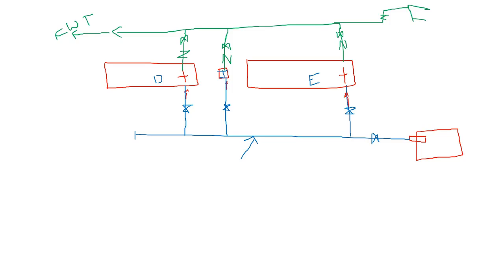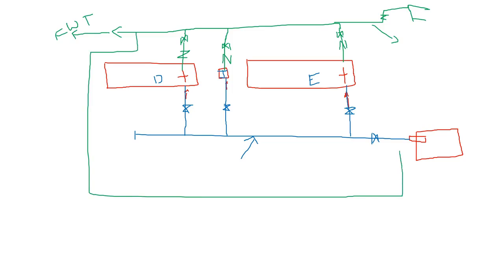Now after that we will have a test line which will be taken from the discharge header and it will go or return to the tank. We will install two gate valves as already told you, and one flow meter between these gate valves. There is a limitation on the distance to be considered between the flow meter and gate valves.